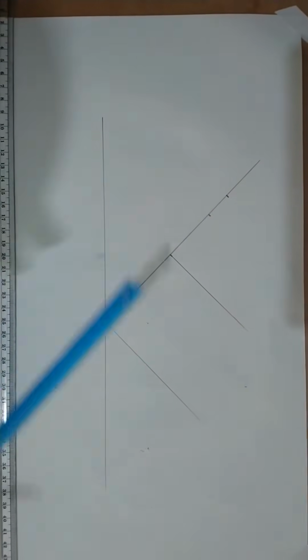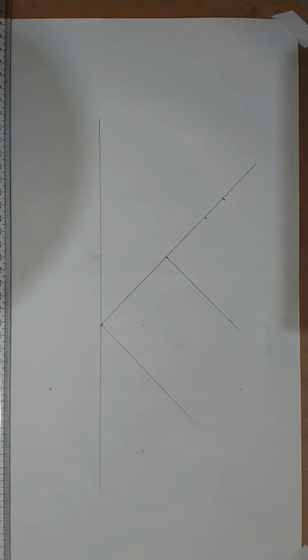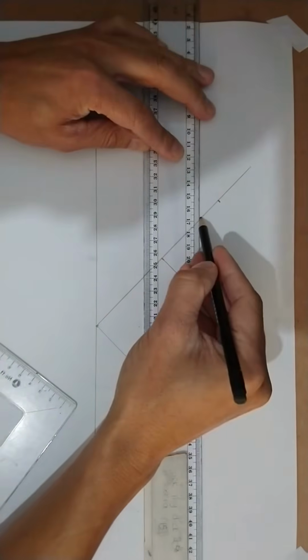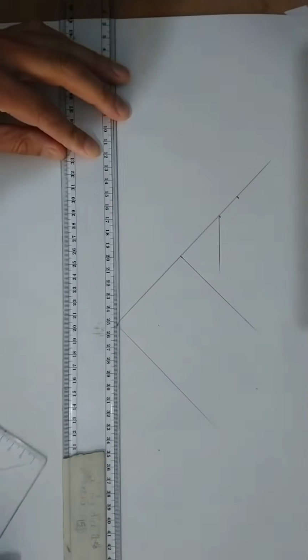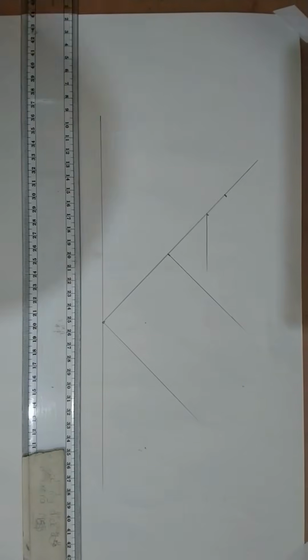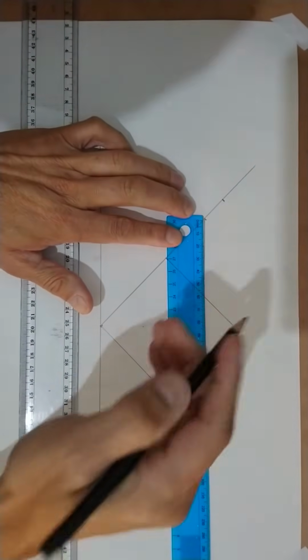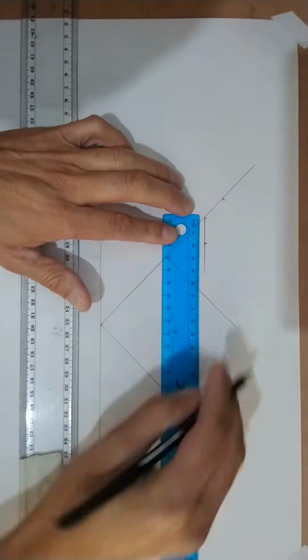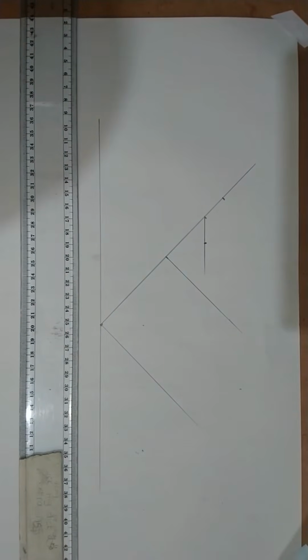Right, that is my one side on a slant. And then I'm going to keep my 45. And if you look at your drawing, then you will see this line goes straight. And when that line goes straight, I've got to measure 20 off on that line as well, because all the sides are 20 millimeters in length.